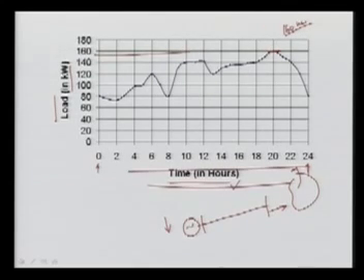Why more than that? Because we must keep some reserve margin in case of some transient or disturbance, where the load may increase, so that the system does not collapse or go dark. So the maximum you can go up to is 160, but the generator is always more than that. Here we may go for a generator of 200 kilowatt. No doubt we always provide two lines, because if one line trips, we can supply the load through the other, increasing the reliability or security of the system. So the rating of the station should always be more than the maximum demand.